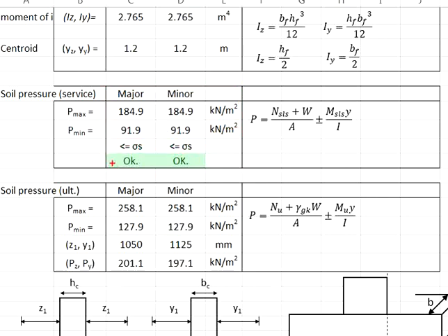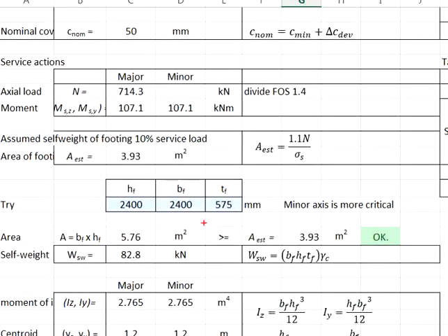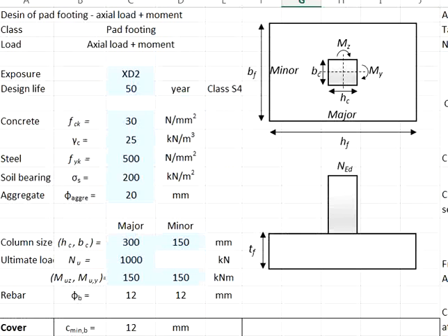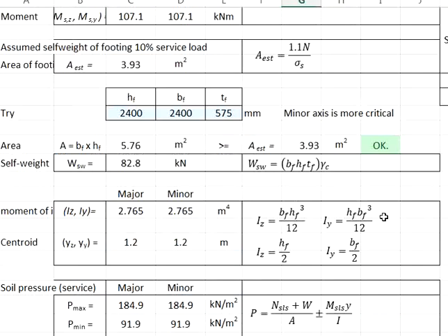Therefore, you will know that the proposed size, specifically in terms of the B and H of the pad footing, is adequate, and you have no issue about the settlement of the pad footing, as you have a higher bearing capacity than the stress exerted onto the soil.